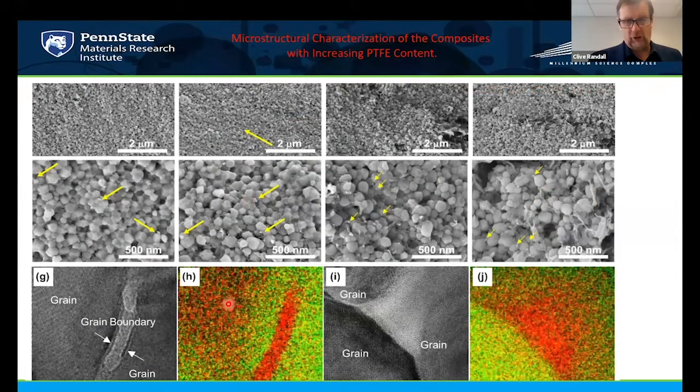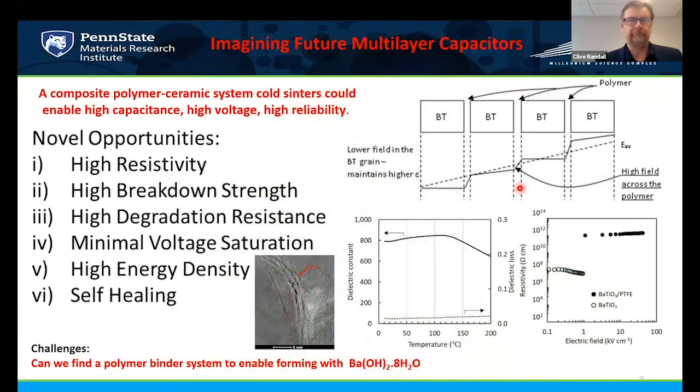Here you can see some of that polymer in the grain boundaries. You can see the types of microstructure. And there's also, driving some of the size effects, small precipitates of barium titanate, which is in combination with this polymer. And so you're getting diffuse phase transformations because of the size effect of these secondary precipitation effects, as well as the densification process.